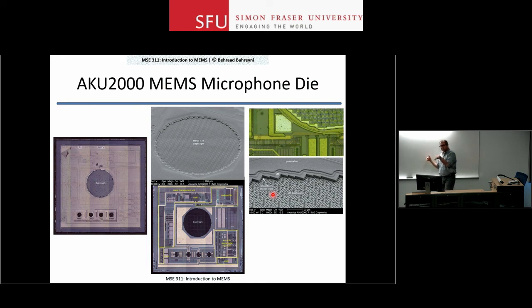Remember, for CMOS, the stress in the thin film is not that critical. The films are all attached to the substrate, nothing is released. But if you want to release those metal layers at the end of the process to create your membrane, you need to find a way to let them release the stress without pushing the membrane up and off the page by too much. So this is what they did.